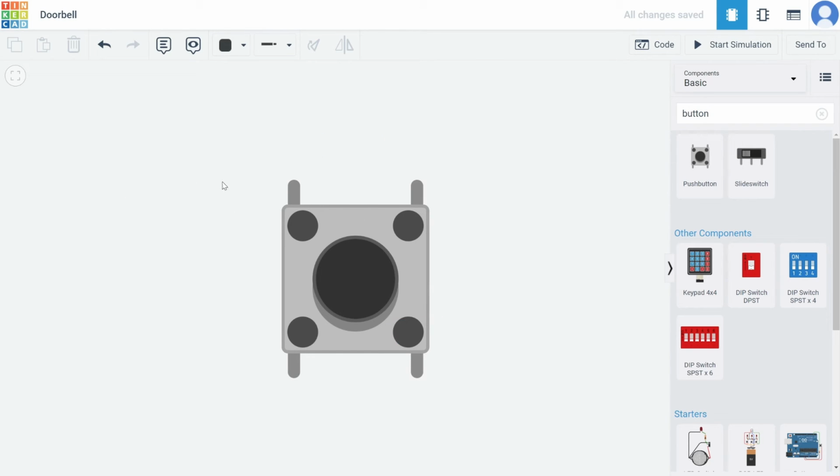out. So you want a wire coming in here and on one of these two pins, and then a wire going off on one of these two pins, and that will not be a circuit until you press the button, and then the circuit will get connected. Okay? So we could just hook this up to a light circuit, for example, where the light is here and then the button is here, all on the same circuit. So as you're holding the button, the light is on, and when you release the button, the light is off.